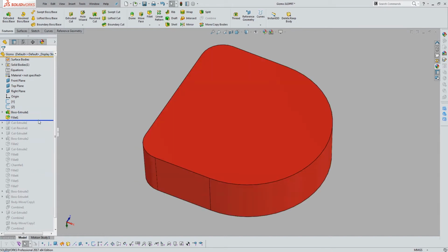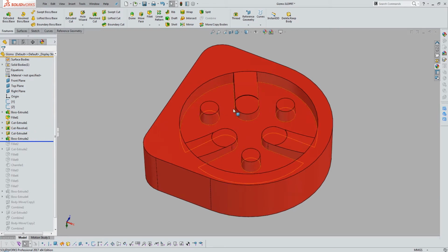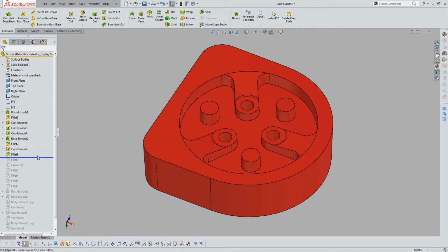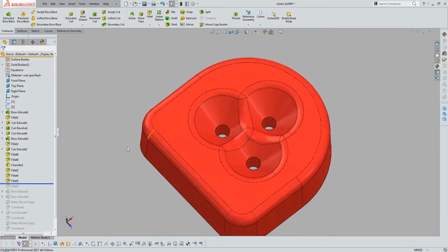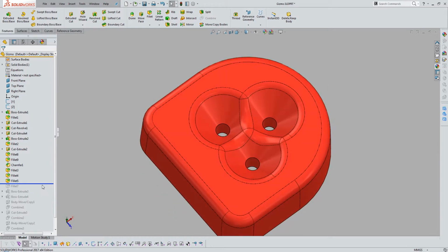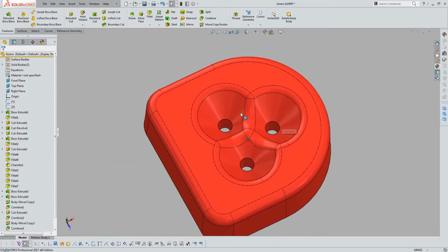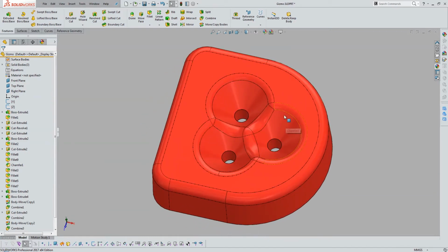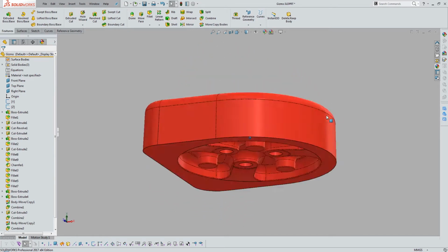Extruded, filleted the edges, cut the bottom out, did a cut revolve to change the profile, cut some holes here, here, and here, and then extruded those two bosses. Some more fillets, some chamfers. Up on top, I drilled some holes and put some chamfers and fillets on there. And all of those features were made using the same tools and techniques that I just showed you on that basic cube or rectangle with the square and the circle cut out of it.